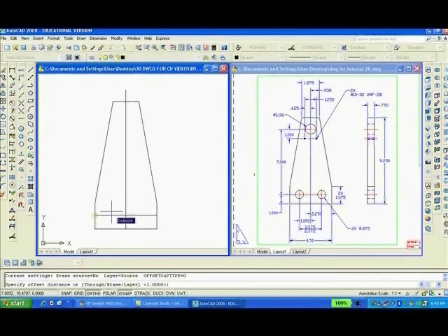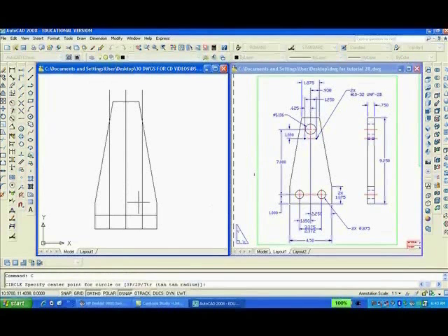Well, there's no dimension given. Well, all right, we'll offset 1.188, enter, that there, and that there. And we've got our centers for the circles. So now we'll hit escape, type C, enter. I'll pick a center point, D, enter, 0.875, enter.